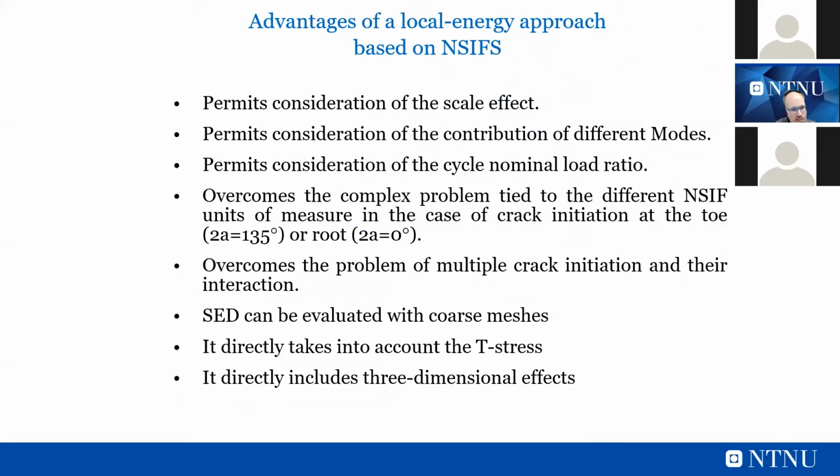And I want to mention the advantages of the strain energy density. The strain energy density is able to consider the scale effect, because it automatically includes the notch stress intensity factor. It is able to consider the contribution of different modes, permits to consider the cyclic nominal load ratio, and permits to consider the effect of different geometrical features, so it automatically includes the effect of the notch opening angle. It overcomes the problem of multiple crack initiation and their interaction, because the volume of material, as I will show later, is in front of the notch tip, and so all the cracks are initiating in that volume. The value can be evaluated with coarse meshes. I will discuss this briefly with you, and this is very important because you can actually use a very coarse mesh